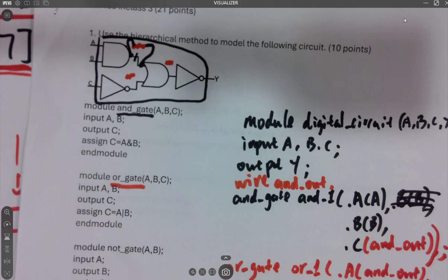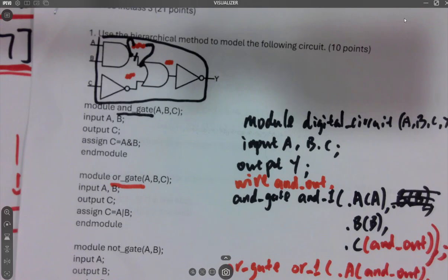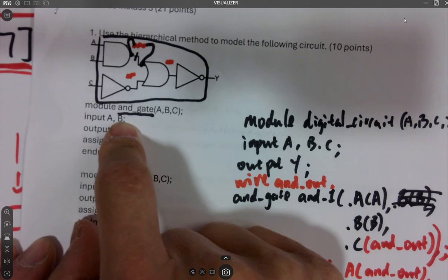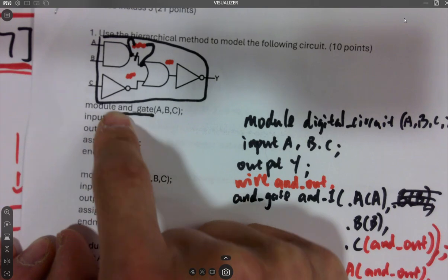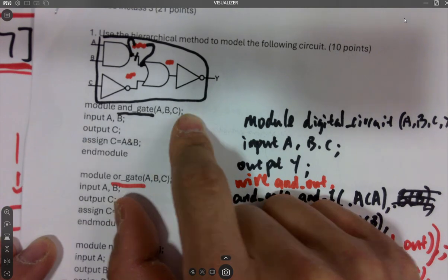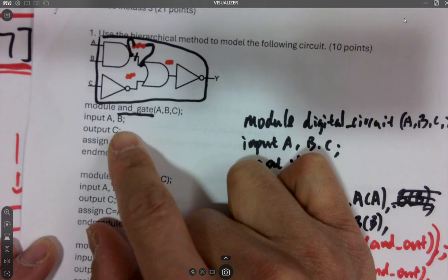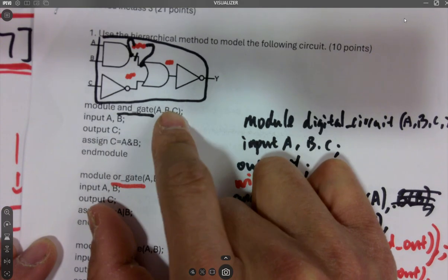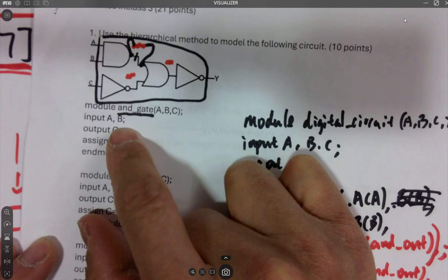Oh, so I need 5 ports. I'll just directly put the parentheses and the 5 ports, right? And after that, I come down here and start thinking about which one should be input, which one should be output. Sometimes I have to modify. I'll come over here to change it, so I don't have to worry about anything in the parentheses anymore. It's just your preference. Both are fine. You can either define it over here in the parentheses, or you can do it afterwards.